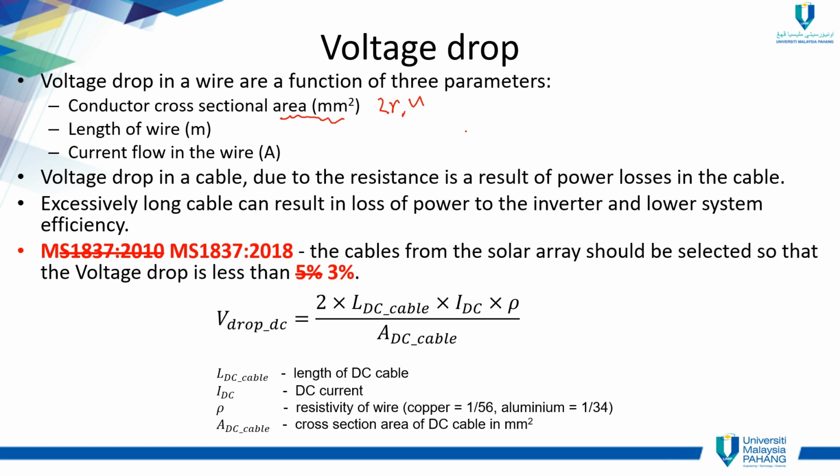apa panggil tu, cable besar. Okay, the bigger size of the cable, it will reduce the voltage drop more lah. But the trade-off is about the cost. Okay, when you use the thicker cable, the cost is more lah. That's logic lah. And then what is the cross-sectional area? Yeah, people are trying to suppress to the lowest cost kan. Contoh, saya bagi contoh. Maybe